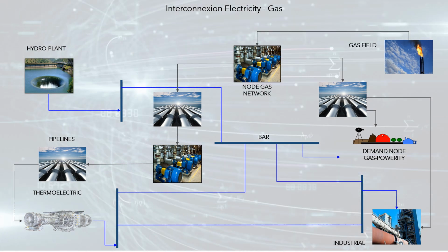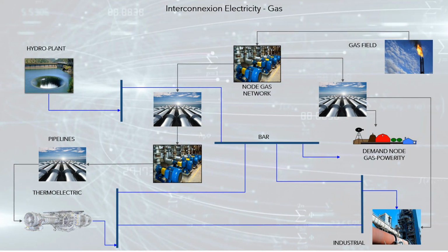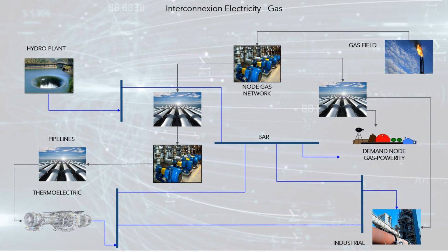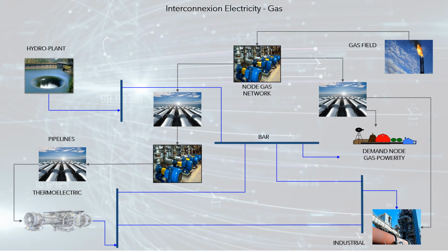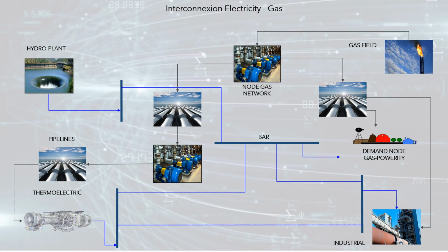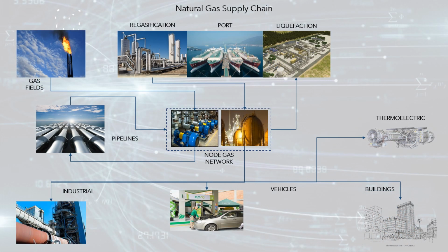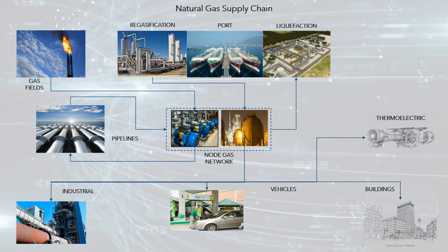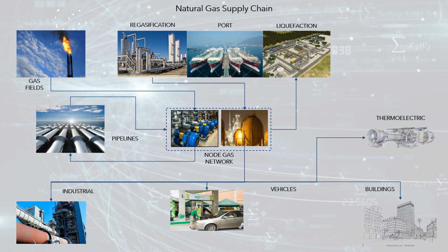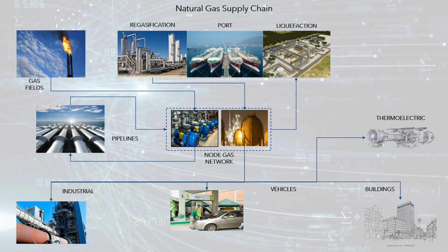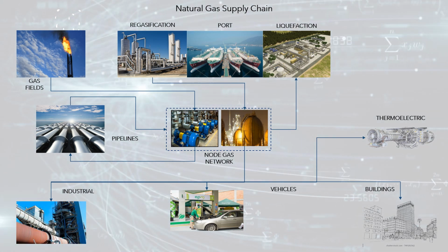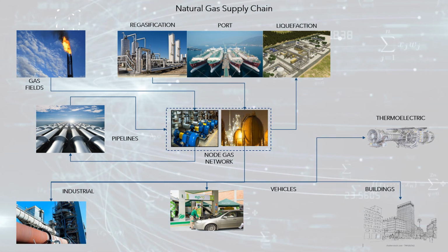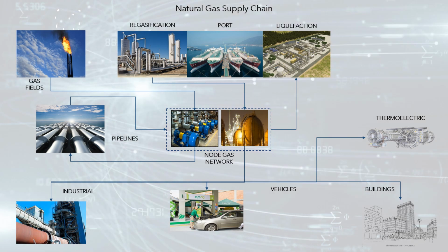The entities of the natural gas system are: nodes, which connect the gas system installations; production fields; consumption zones, discriminated by sector, for example refineries, heavy industries, residential, vehicular, and commercial, and thermoelectric power plants; transport systems, one, pipelines, and two, multimodal transport systems using vehicles; pumping stations, which compress the gas to transport it; and ports, which receive and ship liquefied natural gas, LNG, and have gas storage capacity. Connectivity between the electricity and gas sectors occurs through the demand for natural gas for use in thermal plants, and the substitution of the demand that can occur between gas and electricity.